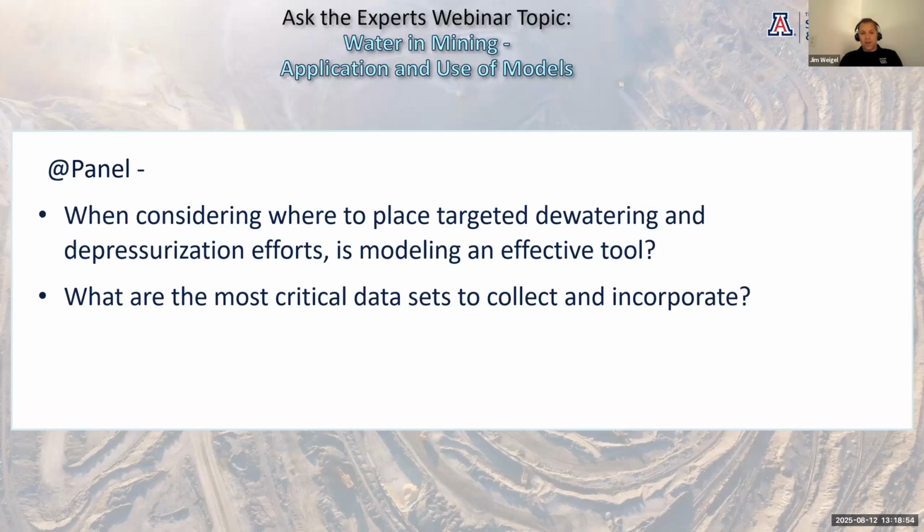Either way, putting in that monitoring system is a needed piece of equipment, even if you were going to do some depressurization, because you need to be able to tell how much depressurization you're achieving. It can also be used to figure out if you need to put in additional depressurization. And it helps you really cement down your conceptual site model and gives you insight into how well your existing groundwater model might be predicting the current system.